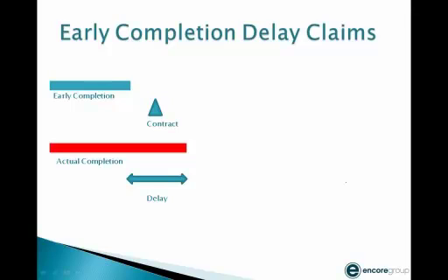We're going to just suppose that a contractor assumed that he could have finished 30 days early, but there was a 60-day delay. There were 30 days that they would have finished early, but they ended up actually finishing 30 days late, right? So you have this delay, and it kind of looks like that. You have 30 days before the contract completion date that you're claiming you were delayed as a contractor, and then 30 days after the contract completion date.